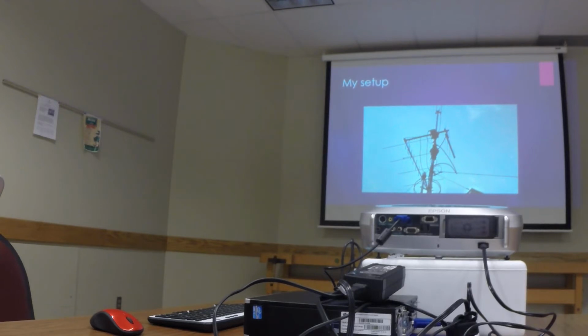Low power is better to try on 2 meters then? Yeah. There are enough 2 meter satellites up there with low power that if you look on YouTube, you'll see a bunch of videos of guys with handy-talkies. They might be 2 meter and UHF, but oftentimes they're just 2 meter handy-talkies with a handheld antenna, much like I showed, and they're working satellites, no problem.